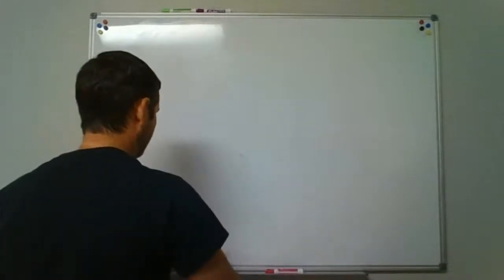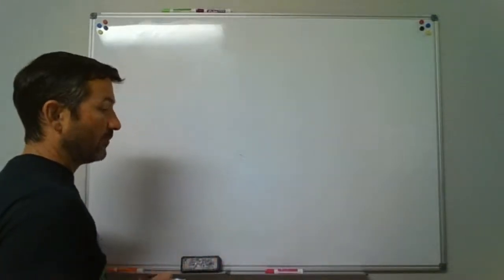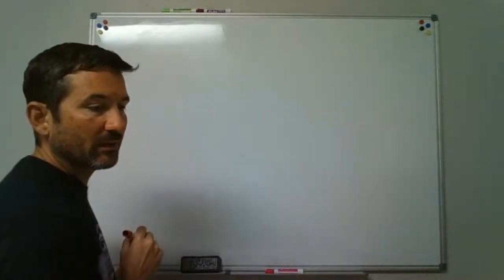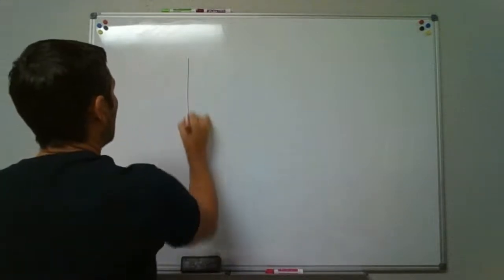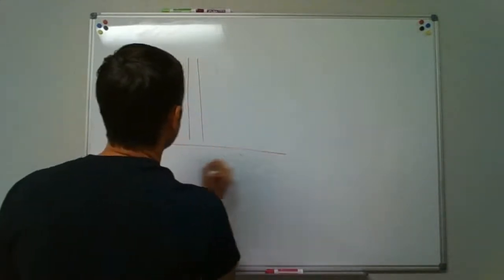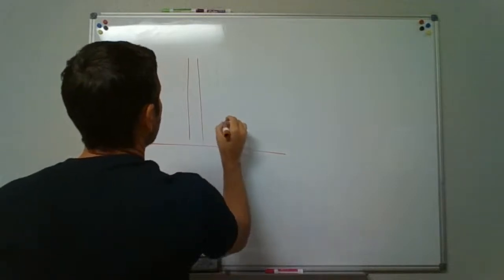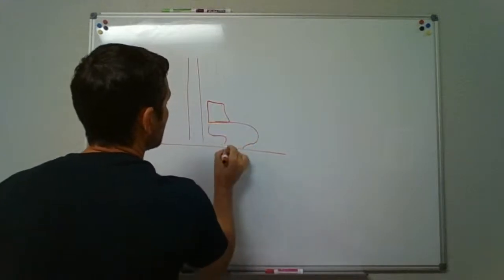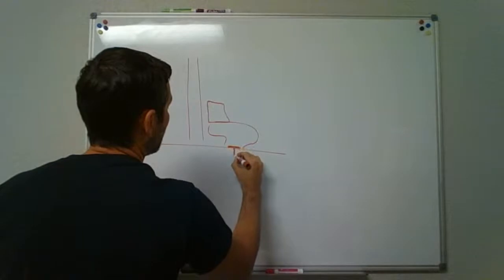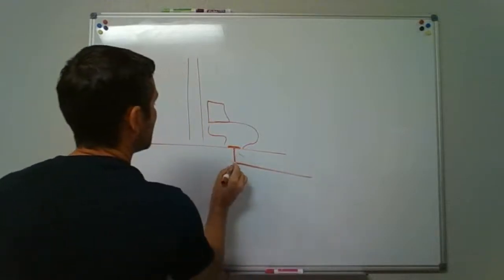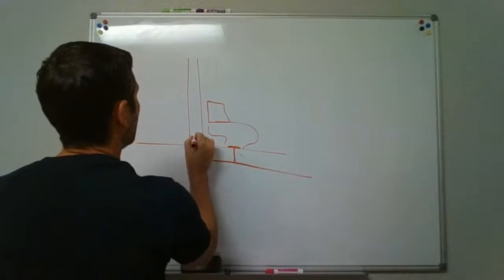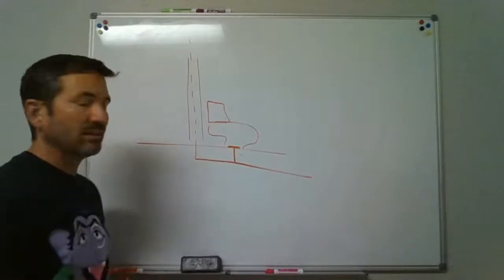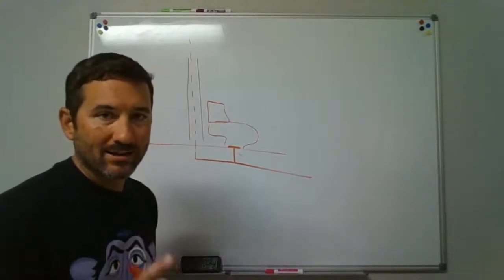All right. So let's just say we wanted to individually vent a water closet. Wall. There's our floor level. Let's just say the water closet was going to be like this. Okay, so we've got a water closet flange here. You come down, you turn out, and let's just say we'll run this back and turn it up, and we'll have a vent up there. Okay, so are we venting that water closet? No, we cannot do that.